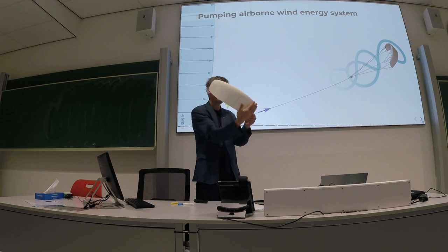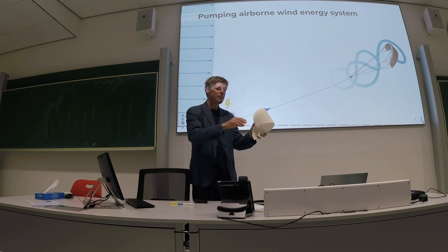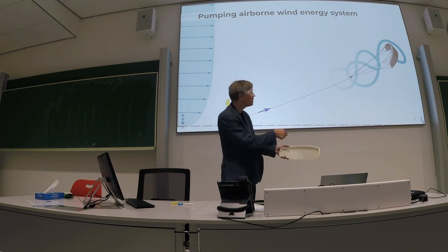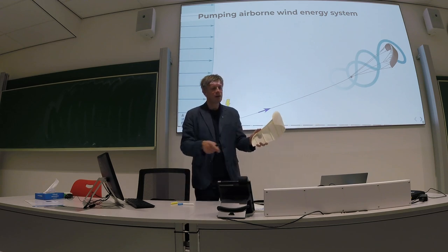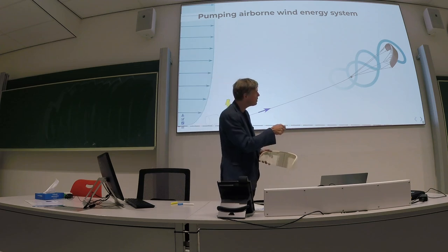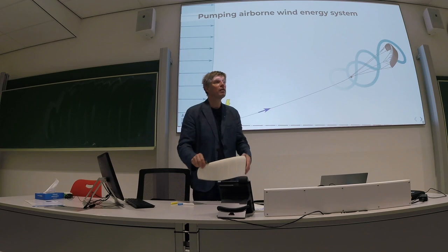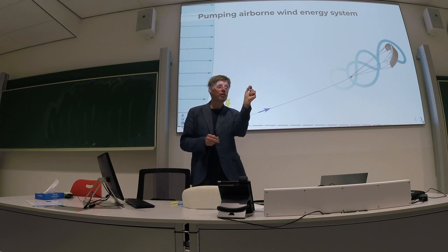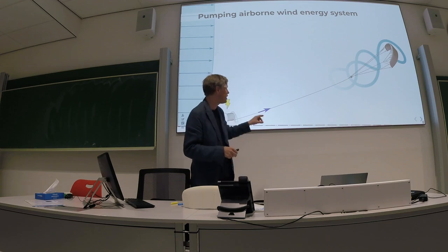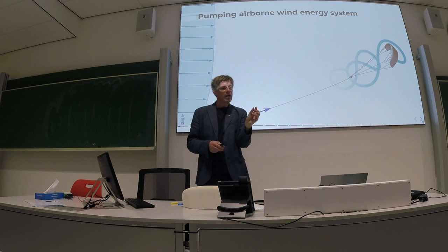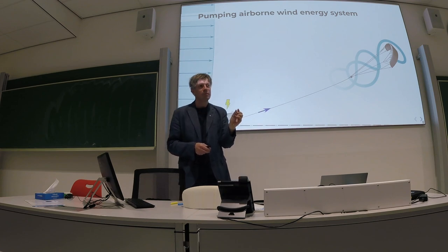That's the wing surface area. All the lines that go down to the control unit are in total 100 meter long. So when you add all these line elements together, you have 100 meter of extra line, but they are much thinner and have lower drag than this main tether. This main tether is now 8 millimeter, 1 centimeter.